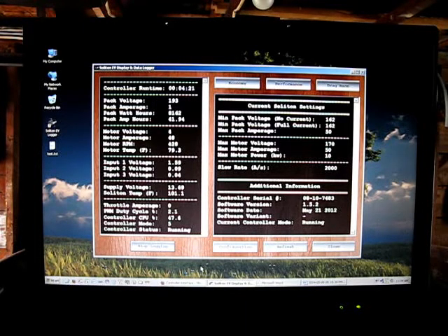So you'll notice that the motor amperage is staying consistent, about 48 to 50. So it's still putting the same amount of current at the motor, but the voltage is dropping. And now we're down to 200 RPMs, 250 RPMs, and continuing to fall slightly. So I'm not sure why that's happening. It's not a motor over temp issue because there's no facility within the Soliton to check the temperature. That's kind of an artificial thing that I'm getting based on that input 1 voltage and calculating.